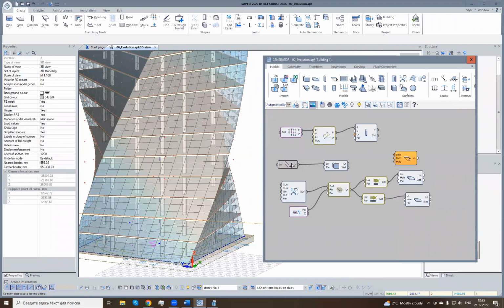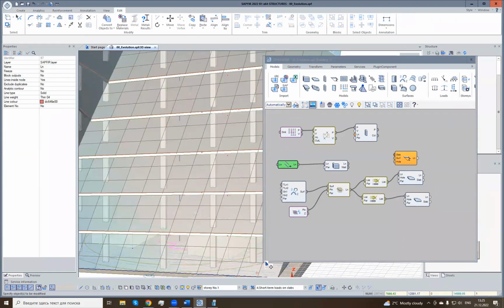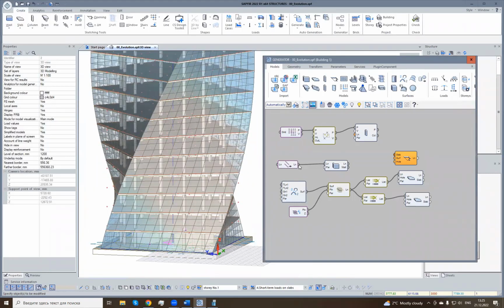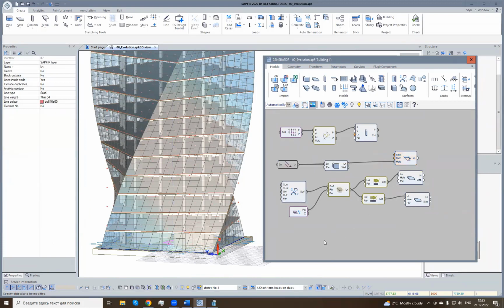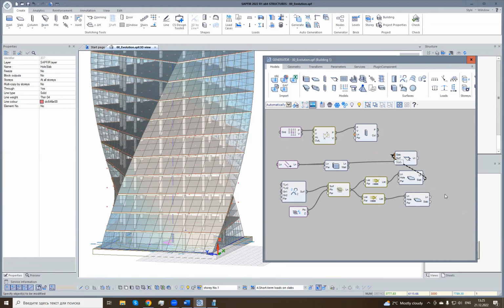Now we remember that we have two contours at 0 elevation, and from this set of lines I can take the lines for the holes in our slab. Now I should specify in what slabs to create the holes. So I will create a link between slab output to the slab input.